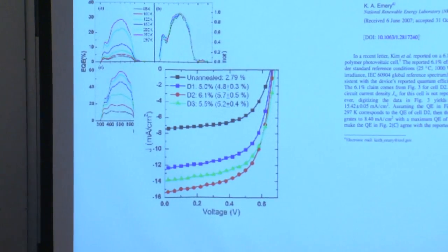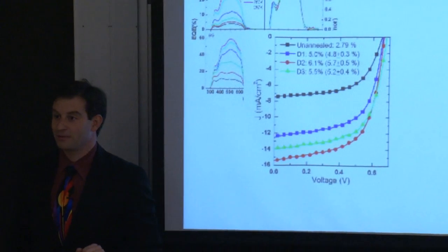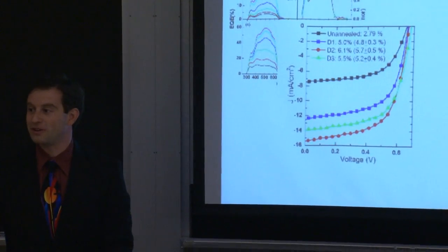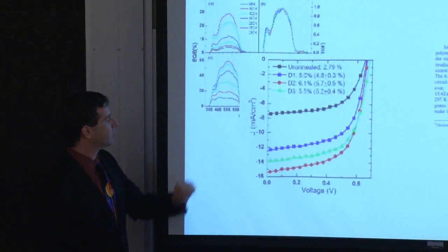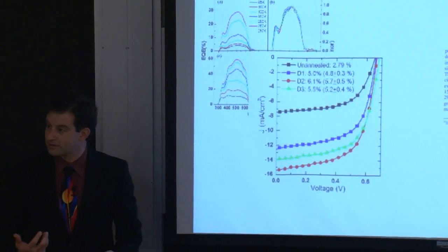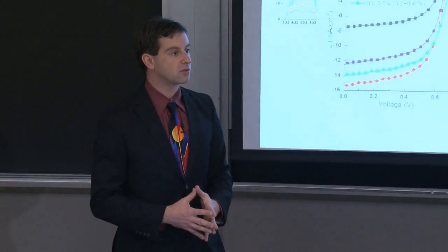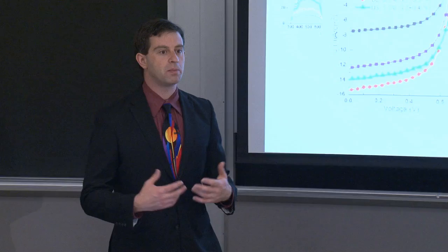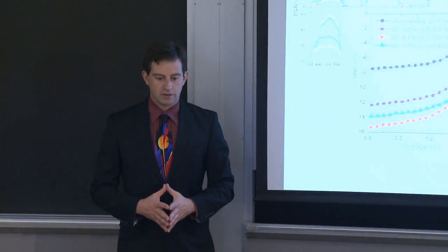I suspect what happened was, in your solar simulator, you were using a silicon reference cell, but your cells were more sensitive to a different region of the solar spectrum. In this particular case, they were more sensitive to the shorter wavelengths, and you didn't have a properly calibrated solar simulator. So you're over-reporting your current outputs. And of course, that's very embarrassing for a group.